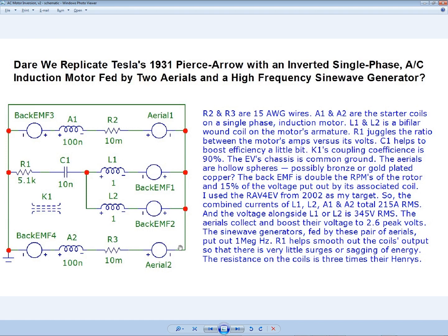See, there's a very interesting thing, and it's backwards to what I thought originally, but now I've realized what is going on in this circuit. This central portion in here of high voltage, low current, is actually an area of negative resistance, so that anything you do here is a gain. Increase the size of L1 and L2, increase the size of R1 to 10,000 ohms maybe, to match what you're doing here. But mostly here, if you increase the size of L1 and L2, the henries, the self-induction, to anything you want, make it a bigger bobbin, put more voltage windings on there.